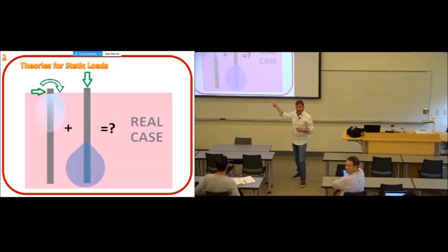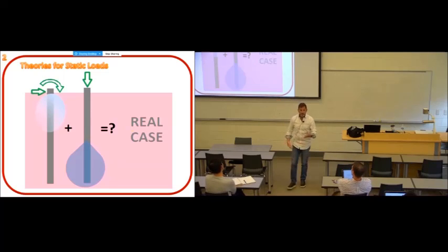And the vertically loaded piles are involving the lower layers. So adding them to get the real answer is okay. In my opinion and practice, it is okay. Now there are theories where they combine both with the P-delta effect, but it's too complicated for real life.